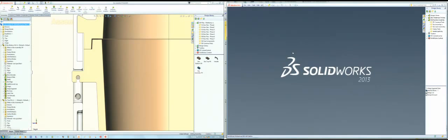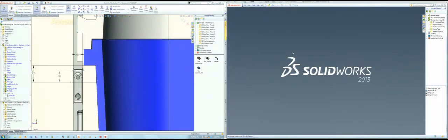Am I getting the right part? Otherwise this isn't going to look right. Latch tab. Okay, so there's the sketch. So I used it, sketched around it, normalized the dimensions so I didn't have something really weird in there, and extruded it. And then made another sketch to make the cutout. So there's a sketch to do that. Now at this point there's no relationship between that latch and the bottom of the box. But it gave me a good guide to make sure I got this cutout in exactly the right spot.